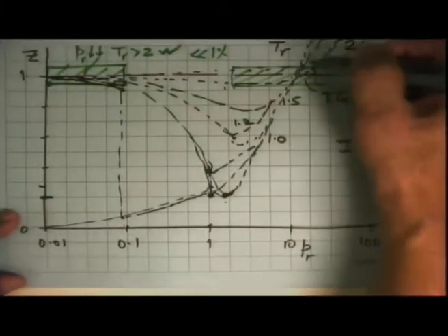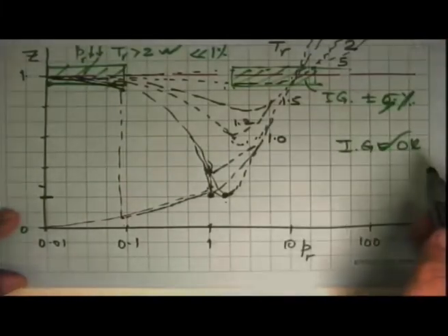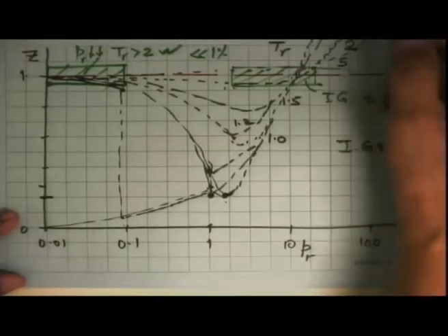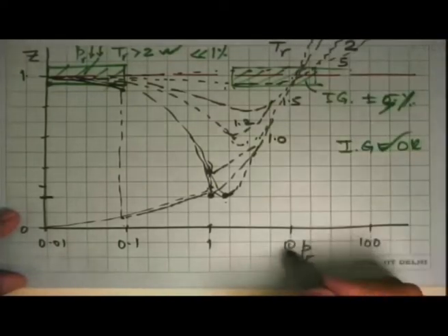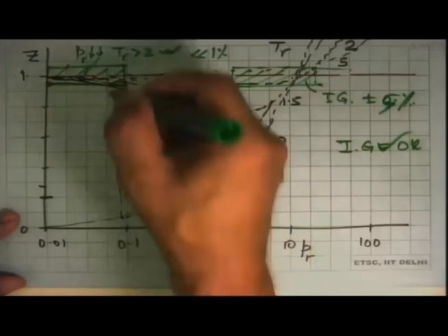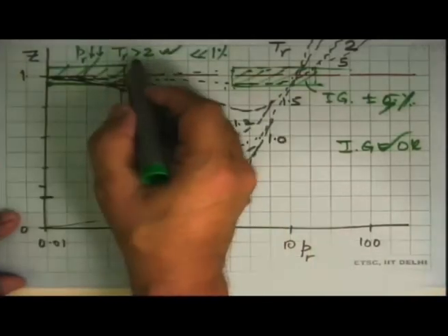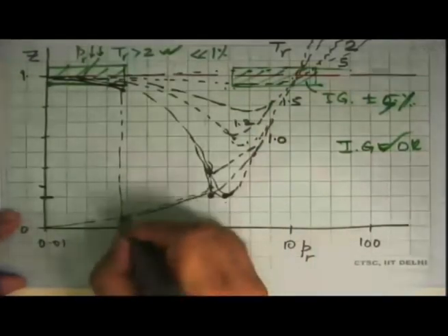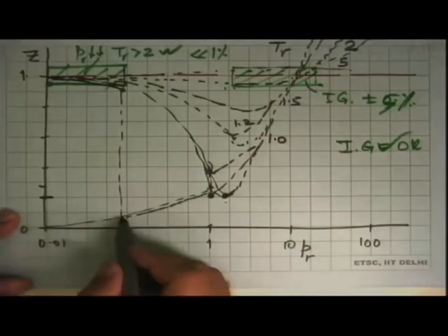And at higher pressures, no, because these curves are very steep, they go up. So we cannot assume anything beyond reduced pressure of 10 to be an ideal gas. And then again, even if the reduced temperature is 2, even if it were a saturated state, then also it is not okay.